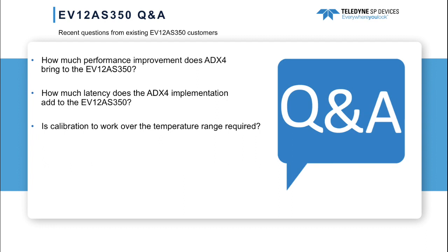The last question here is about calibration working over a wide temperature range, and when we actually do the calibration, that's pre-programmed into these parts. In our final test program, we do set up several calibration settings. So one towards the coldest end of the temperature range, and another that covers the ambient or room temperature and hot temperature conditions.